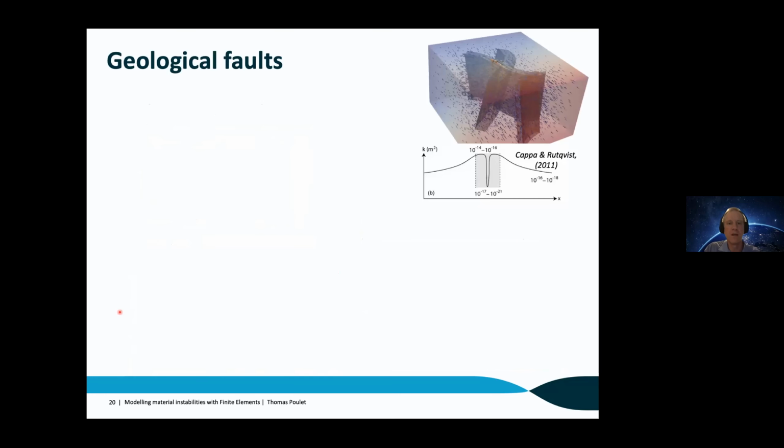So this is some work we've been doing recently. The problem of permeability is that when you have the permeability of a rock around a fault zone, this permeability evolves a lot. As you know, you've got these damage zones where the permeability can jump by orders of magnitude compared to the host rock. And then in the center of this damage zone, you might have a fault gouge with, let's say, clay smearing for some rocks, where the permeability would drop by orders of magnitude.